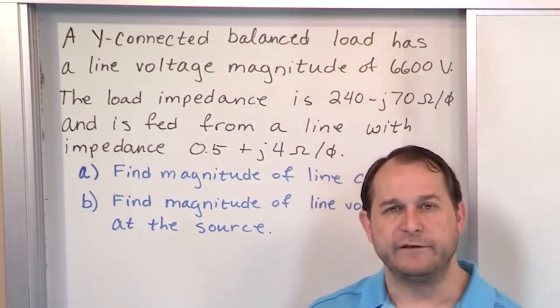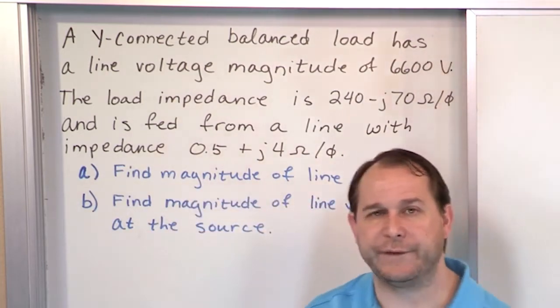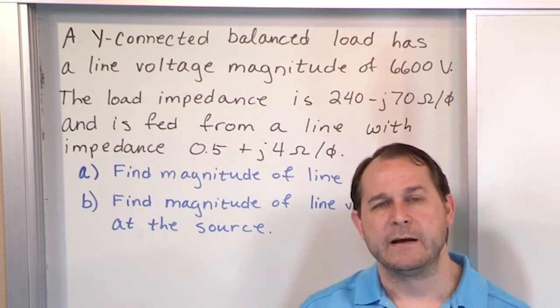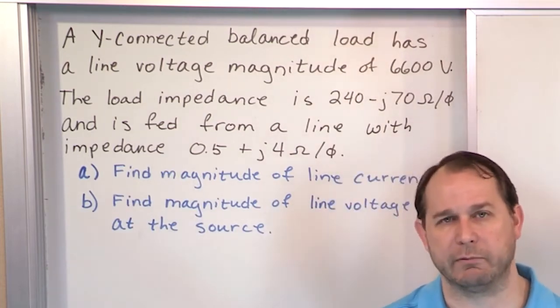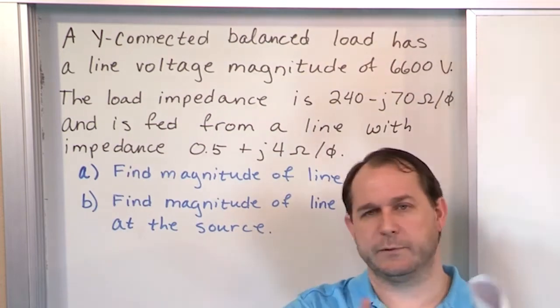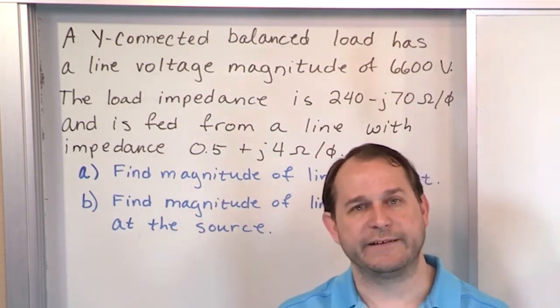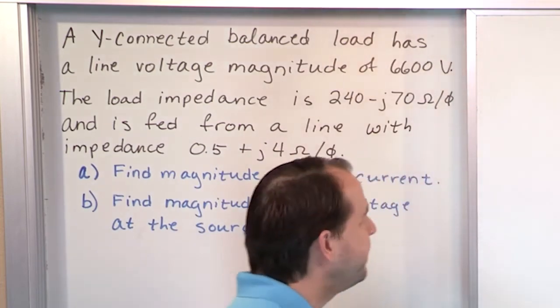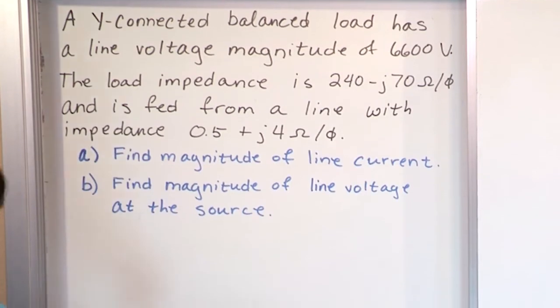So the first thing we need to do for every problem, notice it did not ask you to draw a single phase equivalent circuit. It didn't ask you for that. But that is something you have to do. It's like back in basic physics when they give you a pulley problem. You have two pulleys and you're pulling on them and what happens or whatever. Or an inclined plane. You have to draw it, right? So the same thing for three-phase circuits. You have to draw it because there's no circuit given to you. So the first thing we're going to do is draw a single phase equivalent circuit.